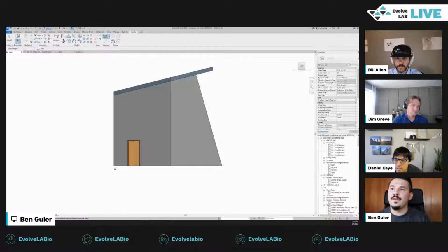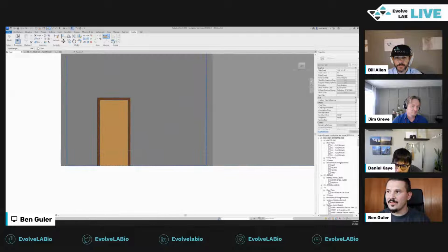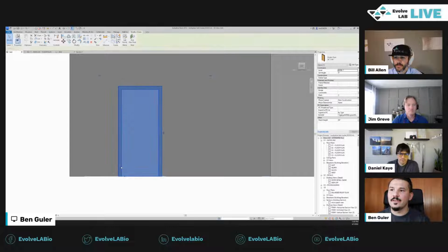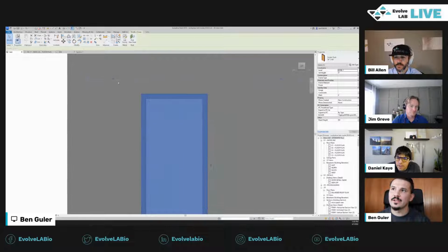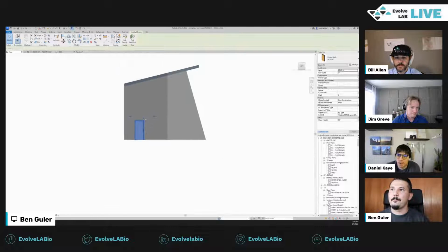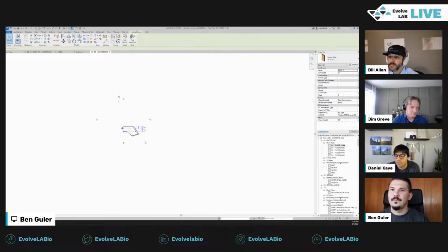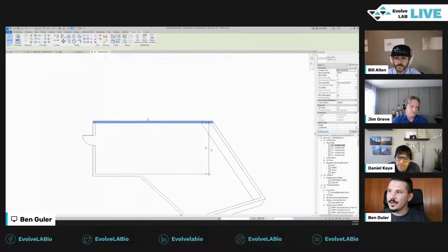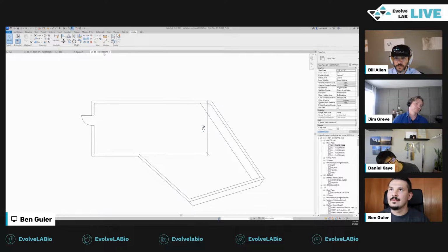I think that's more for the temporary dimensions, not this one. This is the measure tool that gives you that temporary, alternate way of looking at it. It's a different element that's overlaid on top there. I think you're thinking about if I click this, you get these other temporary dimensions that have these grab bar or little anchor points, like in a plan sometimes, where you have an option to click on those and turn them into permanent dimensions. Right, there's a little icon for that permanent dimension button. If I click that, then it becomes a dimension. Yeah, good question. It seems like it doesn't do that.